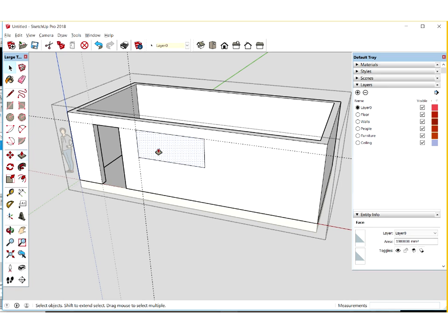And then again, just push pull tool, same method as before. We're pushing that face back into the wall. I'm going to have to jiggle it around. There it is. It's found that back face. If it just misses that back face, it just creates some funny geometry. So you can see there that we've got a door and window. So once you've created a window, put up a green tick and give yourself a pat on the back.